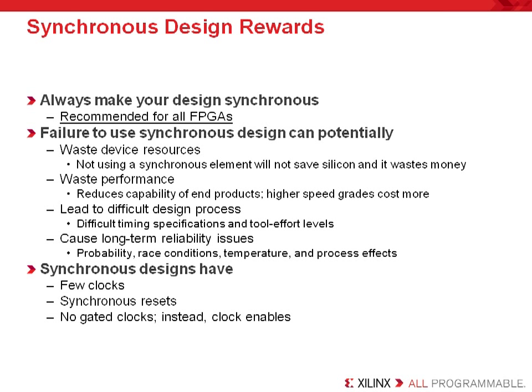Now, if a customer insists on having an asynchronous reset, I usually tell them that their circuit should behave okay as long as the reset is global, but I never allow a local asynchronous reset in a design. For more information on synchronous design practices, check out the Synchronous Design module as I mentioned in the Essentials of FPGA Design course.